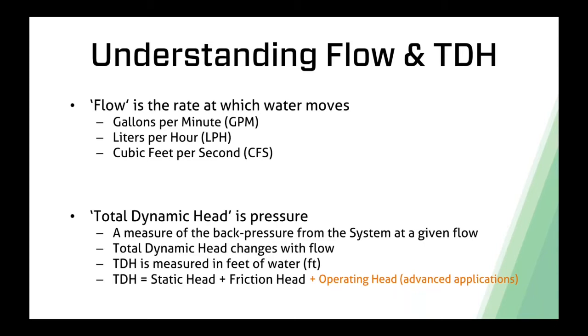Total dynamic head, as I said, is a measure of pressure, but we measure it with a unit of feet of water. And sometimes we'll shorten that just to feet. We'll talk about, this application has 20 feet of total dynamic head. And what we mean is the total dynamic head is equal to 20 feet of water. And it can be a little bit confusing because when we see feet, we think about a length measurement. We don't think about it that feet of water could be a measure of pressure.